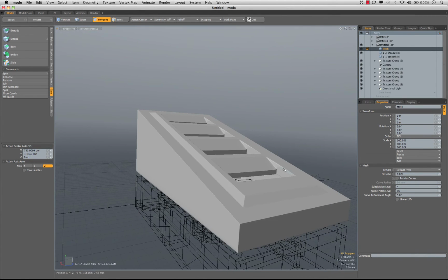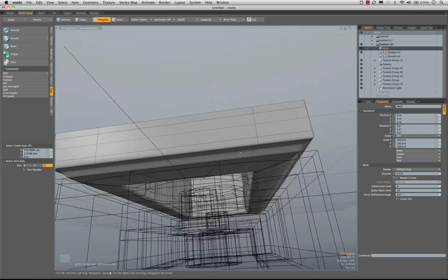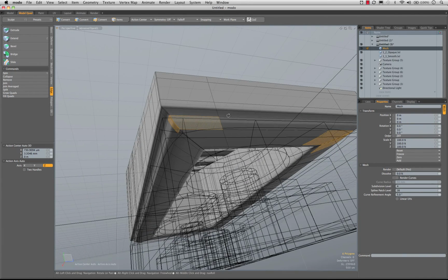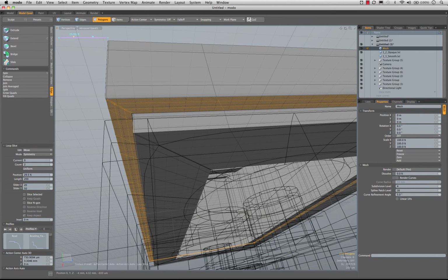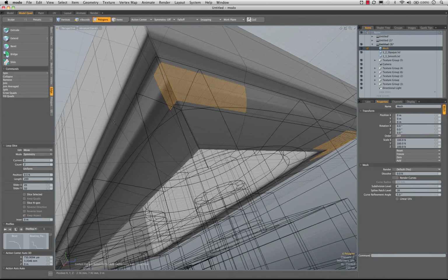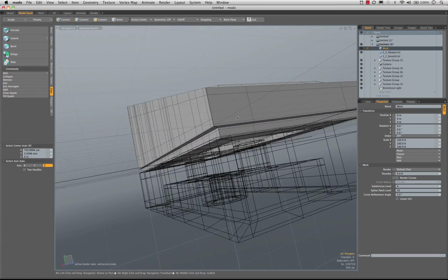It's looking relatively close. We may need a single loop slice along one of these. Actually, no, I think that's good. Well, we do need a couple loop slices that we haven't added yet, down here and around here on those, and then one set around here too. And I should be running these a little bit looser. Let's back up here on these sections since we have kind of a uniform scale that we've been keeping to these, keeping them at 2%. Just keeps them a little bit rounded.